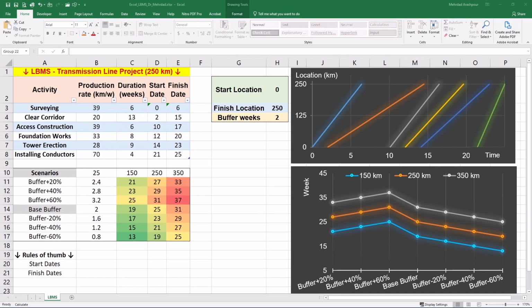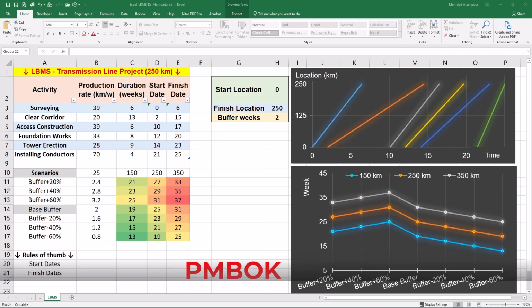We know that Location-Based Management System or LBMS, Critical Path Method or CPM, and Takt Time Planning or TTP are three popular project management methodologies which aim to improve project efficiency and delivery. LBMS is ideal for especially repetitive projects, CPM is better for managing dependencies in unique or complex projects, and TTP is most effective in achieving lean and synchronized production flows. For successful project planning, it is recommended to use PMBOK principles and linear project software such as Tilos by Trimble or TurboChart to achieve greater precision and reliability.